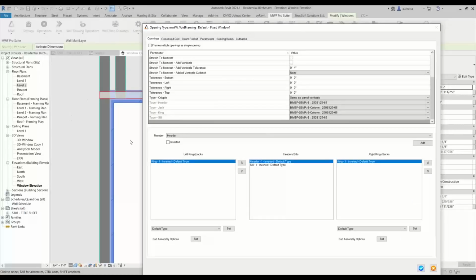Like I said, if you want to go into the opening or towards the center of the opening, it will be negative. If you want it to be outside the opening, it will be positive. So we are going to go negative 0.5 inches. We'll click outside, copy, and paste, and paste, and paste, because it is happening on all 4 sides, and all 4 sides need to move towards the center.